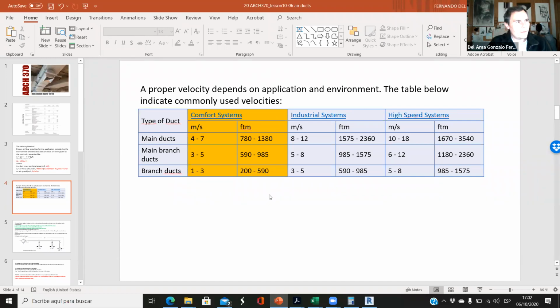Okay, so if you look at the TDS center, the classroom, the 110 classroom, where we used to have this lesson, there are exposed ducts there. And even in the computer lab, you can see that we have two round ducts on one side and the other side, and they are exposed. They are not hidden by the false ceiling. So the air velocity should be close to 200, 300. But the ducts that are outside the building on the roof should be around 1000.